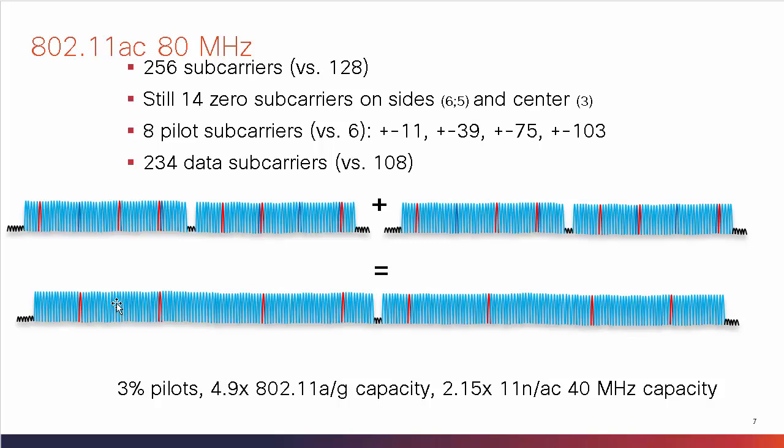What is the consequence of that? Well, the consequence is that if you want to use an 80 MHz wide channel, you need to have a signal quality good enough that you can do without knowledge of the noise figure between those pilot frequencies. In other words, if you have a lot of noise in a 20 MHz transmission, you have enough pilots to have a good understanding of this noise figure throughout the 20 MHz transmission.